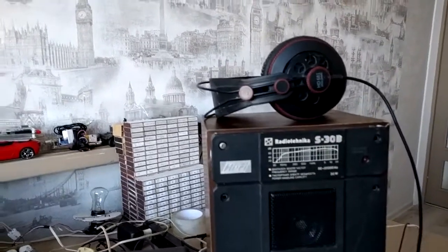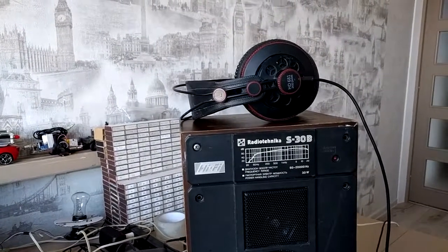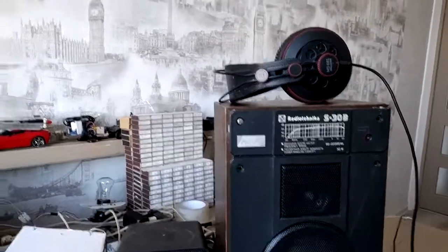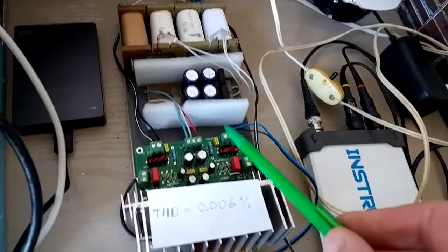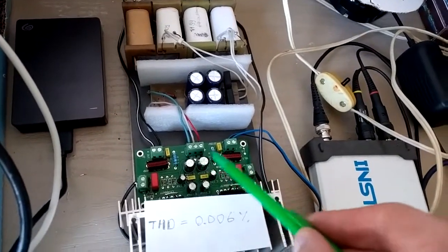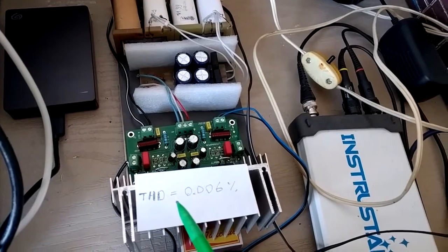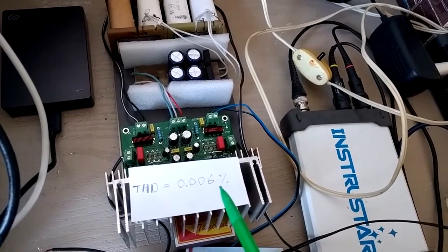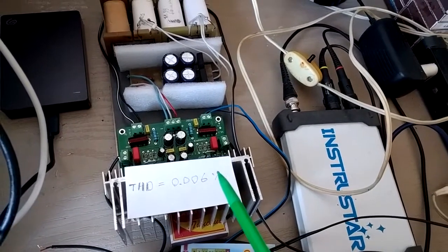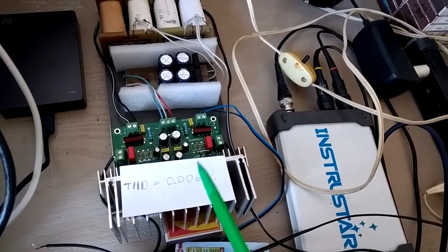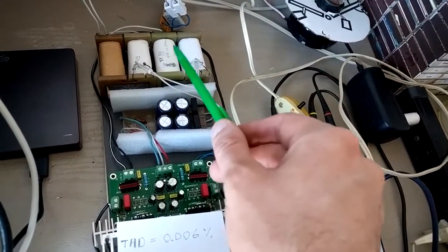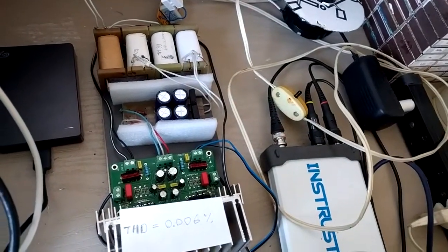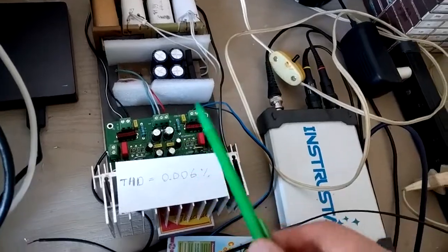So the headphones probably are providing the best sound quality subjectively, but we will see if it's true or not using our measurement techniques. I also have built the audio amplifier. From the previous test I found out that this one is the best audio amplifier, with total harmonic distortion of only 0.006%, which is almost the same as if I replace this amplifier with a single piece of wire, so as good as the wire. We just added this classical style power supply, a bank of capacitors, and the amplifier itself.